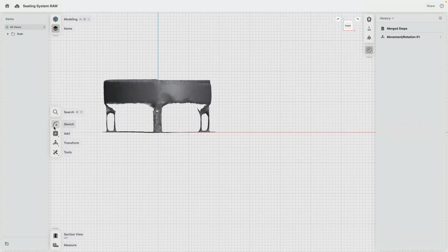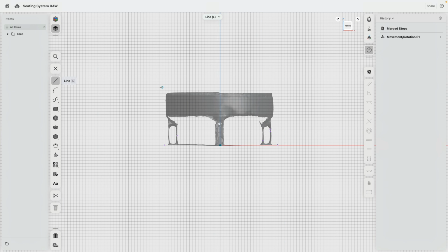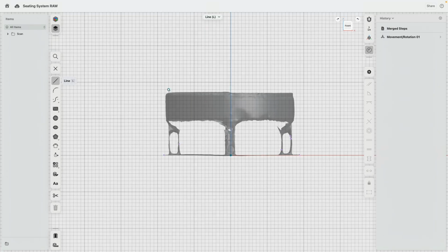Go to front view, then we create a new sketch. And again, now this is a circular piece that's revolved, so we only need a cross section. I simply can start somewhere here on the z-axis, click and go left and go down and go horizontal and go back up.